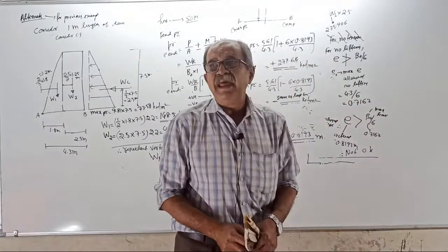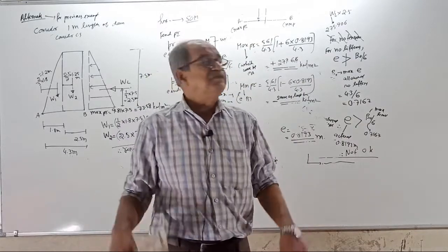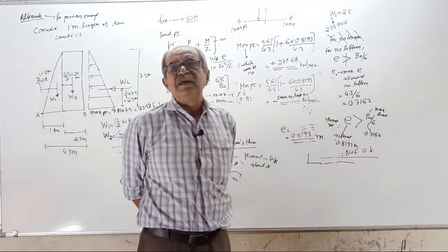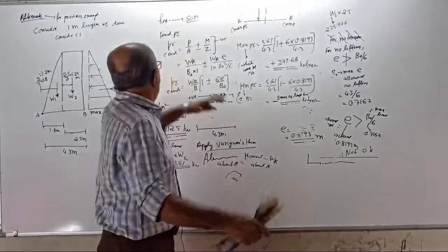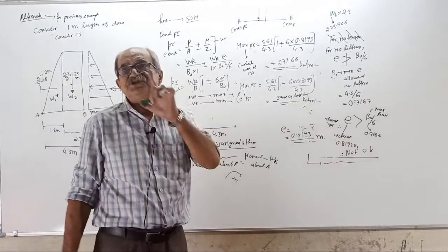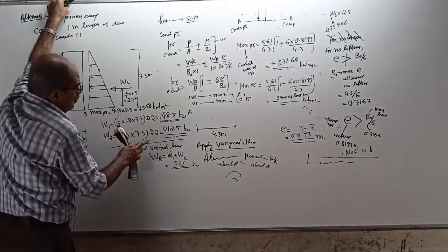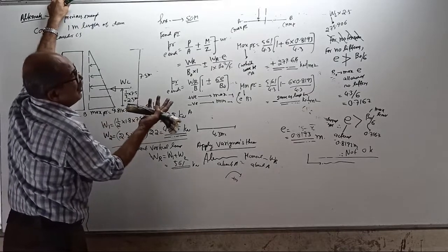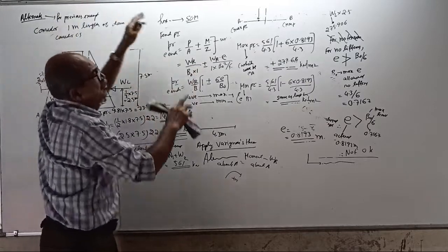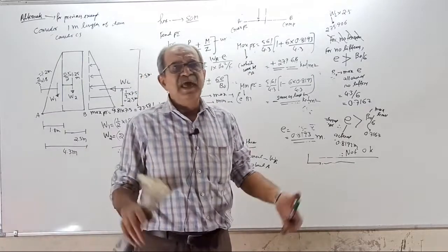Okay. Now, make a note. So, this question, practically, you have to increase the base width. Second one: maximum pressure should not exceed the SBC of soil. And whatever lateral load is there, that will try to cause sliding. So you should check for sliding, for a sliding force of WL equal to, where is it? Somewhere, I forgot. Somewhere there, WL equal to some kilonewton. Yes, 275.906 kilonewton.